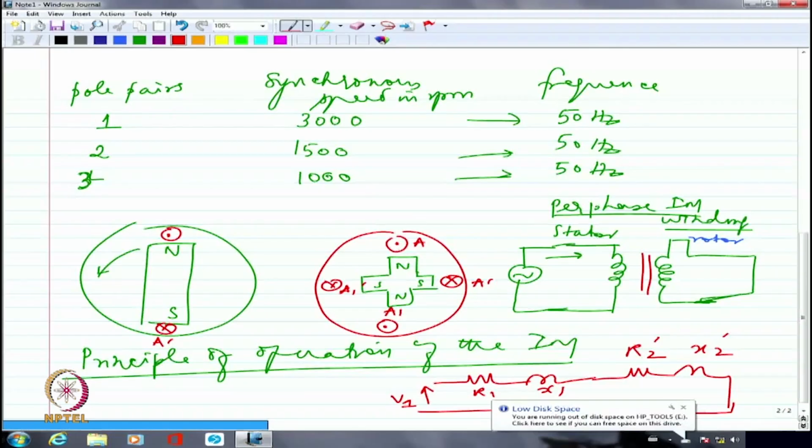So this will take place until a beautiful balance happens in such a way that the frictional torque is overcome. If I don't have any load on the rotor shaft, the frictional torque will be overcome with a small torque developed by a small current flowing, by a small induced EMF, which will come in handy if there is a small relative velocity.